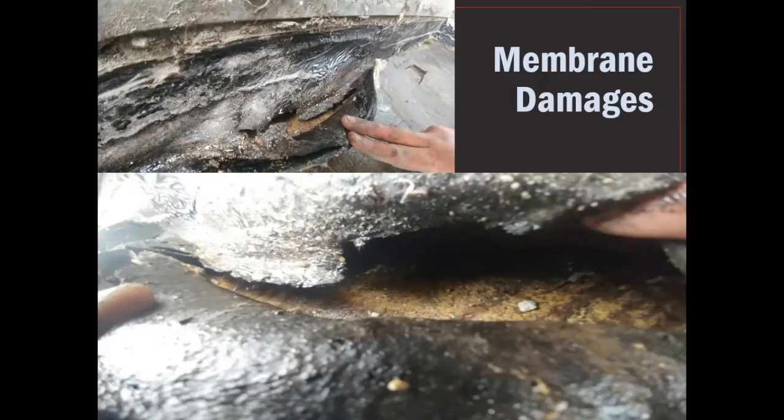So again, when the areas are exposed, if there's any splits, cracks, openings in the membrane, that can be areas where water's getting in, even in cases where there's not heavy rainfall. Even if it's lighter rainfall, if there's openings as severe as some of these ones, it can cause potential leak issues.